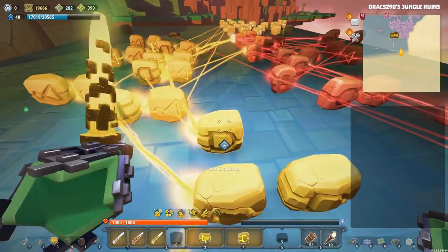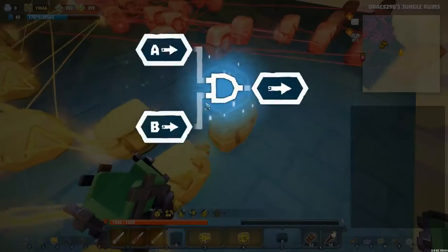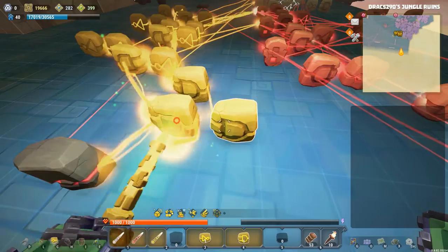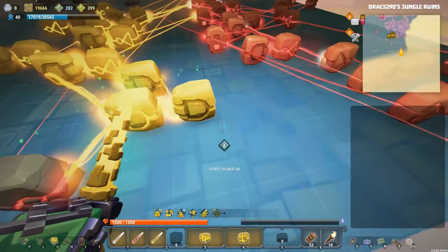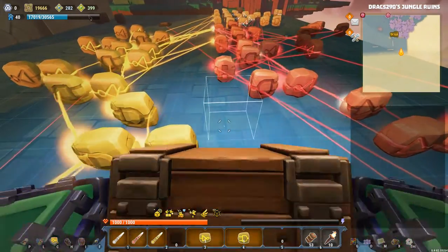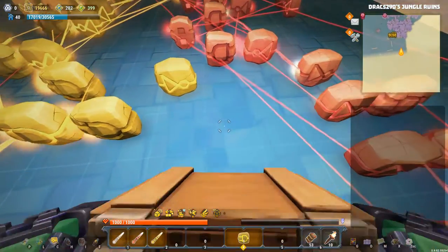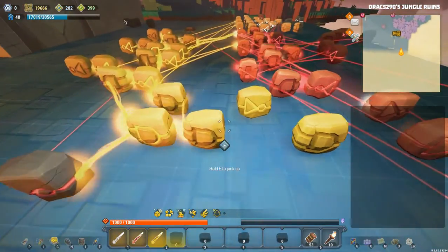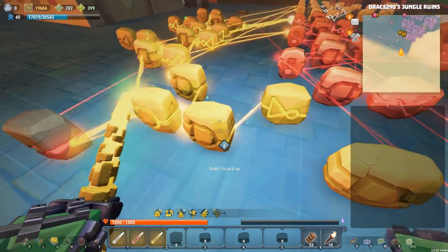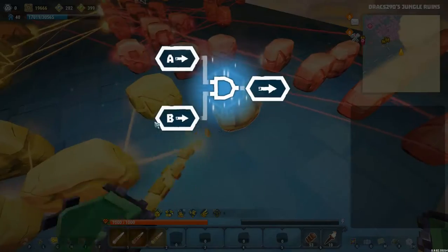And then we're going to AND these two things together. So we're going to AND this with that at the A side, and then this guy is going to go into the B side down here. Perfect, just like that. Now finally we're going to turn this into a rising edge pulse by adding in one NOT gate and one AND gate, and doing this as we've always done rising edge pulses, by hooking this AND gate into the NOT gate and into the B side down here.